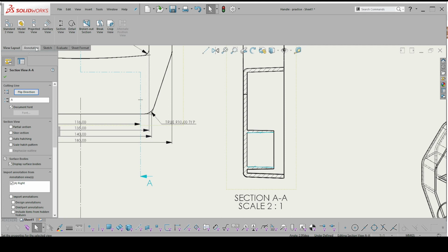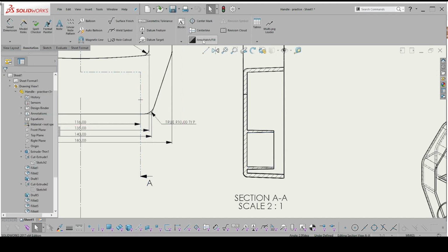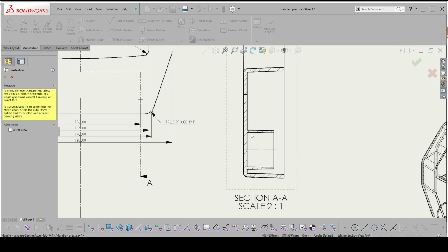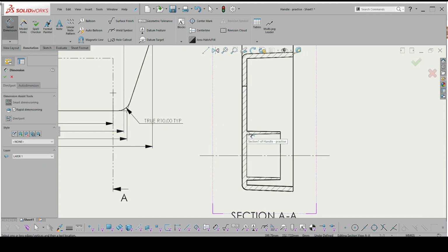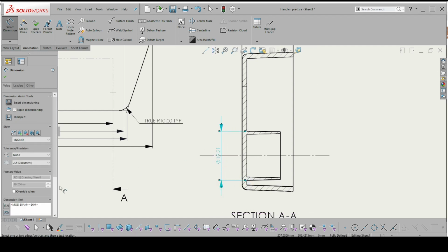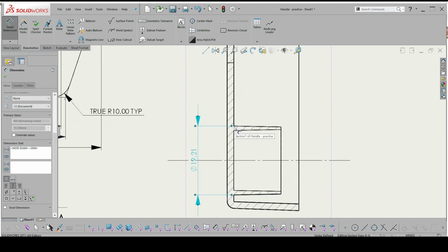So I'm going to select those two, go to annotation, center line. Oh, sorry, it won't. It sometimes allows you to select the lines first. In this case, not the case. There we go. Okay, so there's my center line. I can drag this out, and now I can dimension the diameter at root, which is this one here. That's given me the diameter symbol. If that doesn't appear, then you should be able to come down on the left hand side here and select the diameter symbol. And then the other thing I need is a root wall thickness.